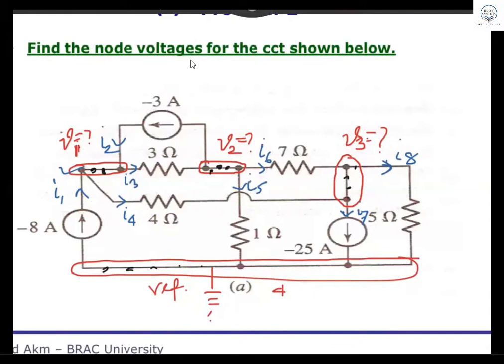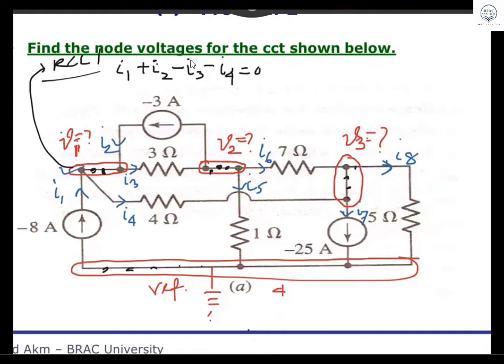Okay, good. Thank you very much for asking this question. Now, in this case, if you go to the KCL one, how many currents are there? Altogether 4 currents, and the 4 currents will be like this. I1 is coming in, I2 is coming in, so I2 also plus. Anybody got any question like him, ask me immediately, then we can solve it. I3 going out, I4 going out, there are 4 currents. That's it. This is your KCL1.